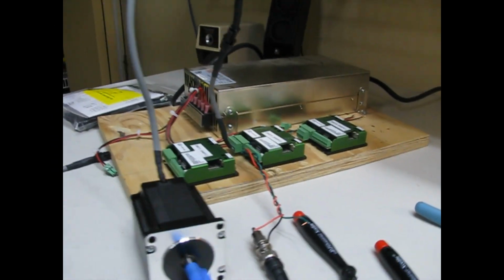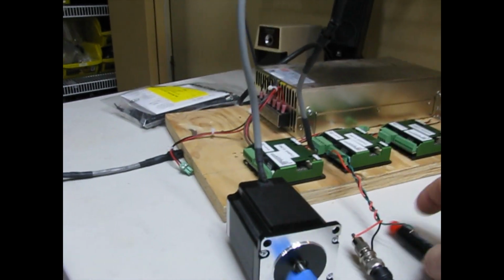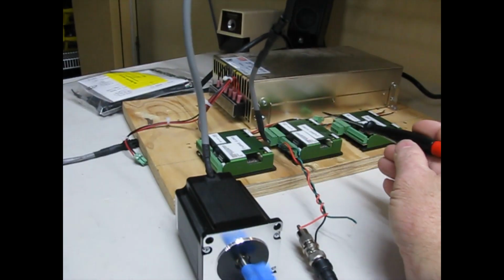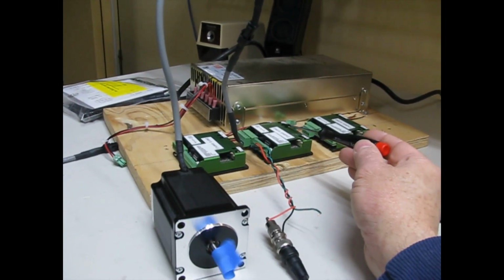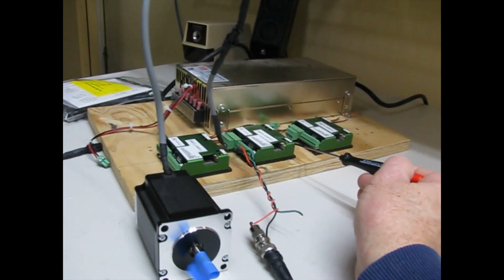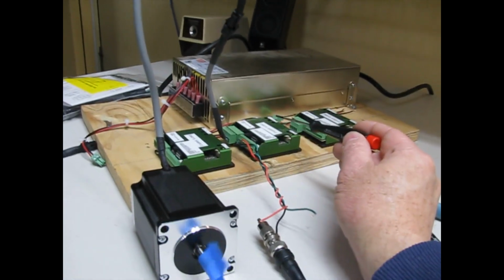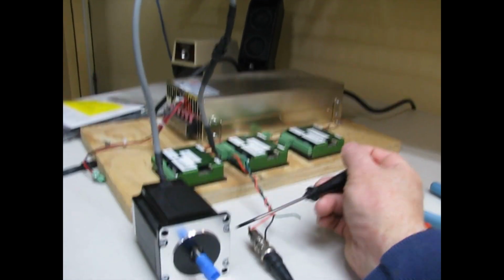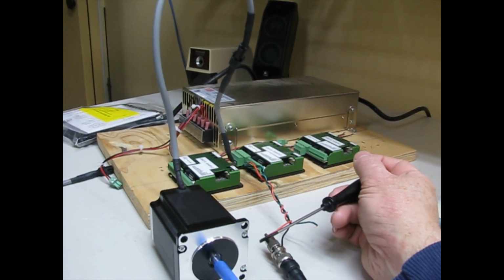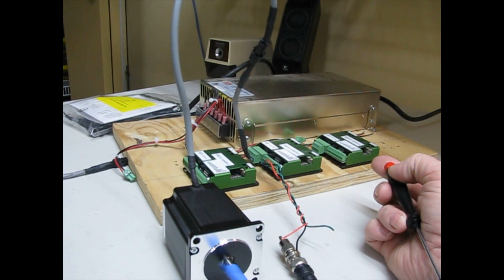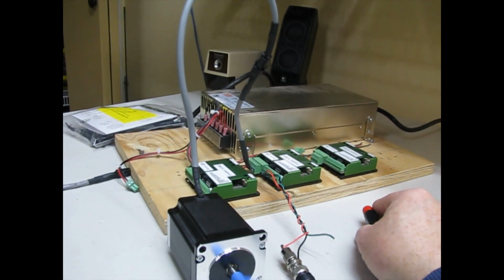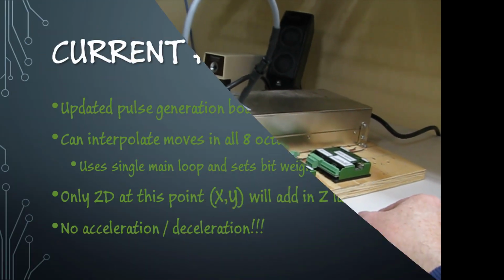I hooked my signal generator up to the stepper drive with a 1 kilohertz square wave, and it was just as noisy. And I read the manual a little more, and I remembered that there are a few pots on here to tune for smoothness with low speed signals. So I did that, and it quieted down quite a lot. I'll cut in some actual audio now. So that is what I did there, and as you can see, that is much less rough.